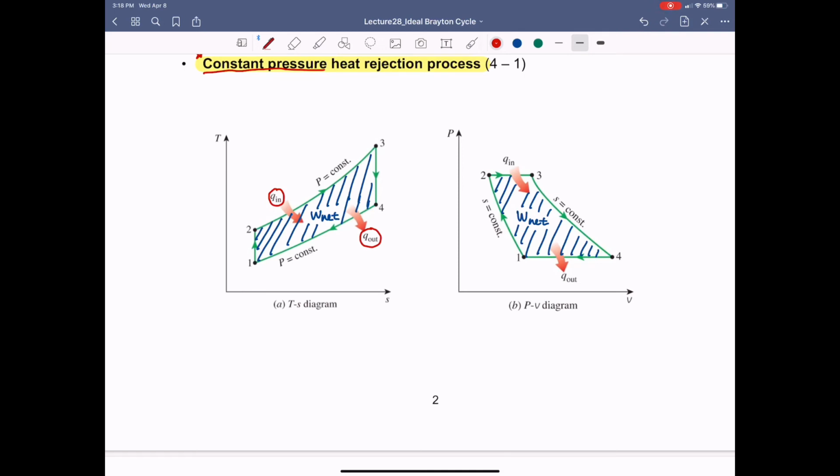But when you go back to the Brayton cycle or gas turbine, what matters is not the volume change, because that is a kind of continuous flowing condition. What you have to look at is how the pressure is increased in the compression process. So the key design parameter in the gas turbine is how pressure changes from the low, almost the same as the atmospheric pressure, to the higher pressure as a result of compression.